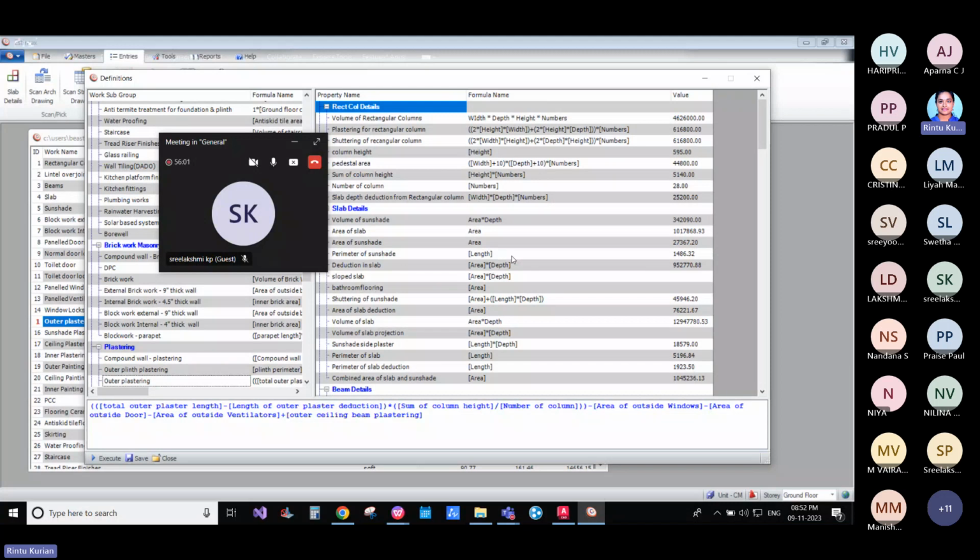So what we do is we'll create a property in property builder corresponding to the slab quantity, and we'll create one for the beam quantity, and we'll connect them in this particular equation portion. So you can see here, these are different properties of work we have created. We are linking them either by subtracting, multiplying, dividing, and all those necessary calculations are done in the equation portion. And filtering of these data is also done in the property builder.